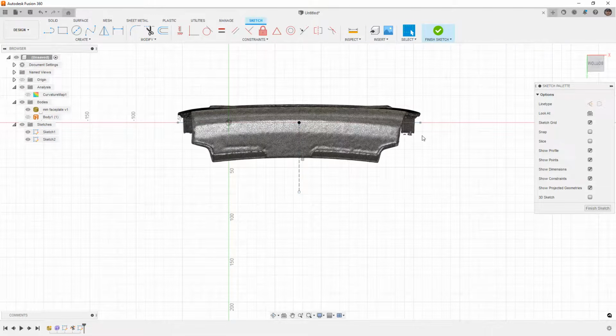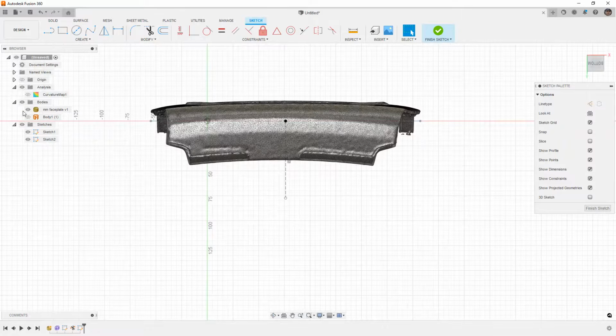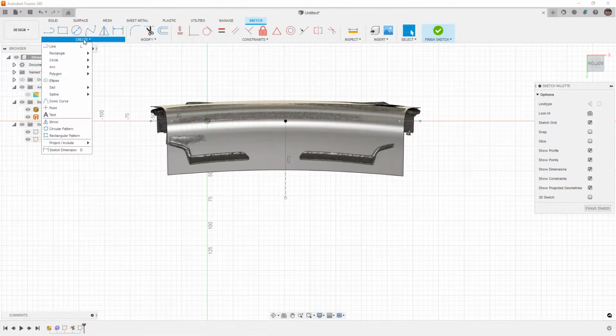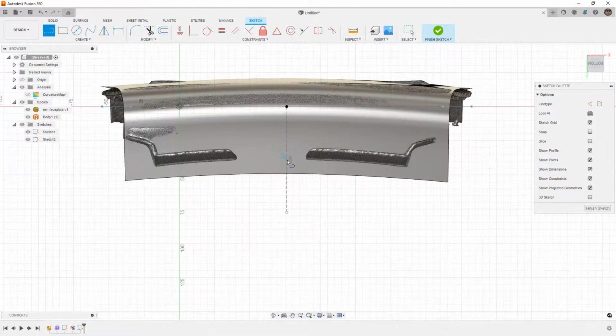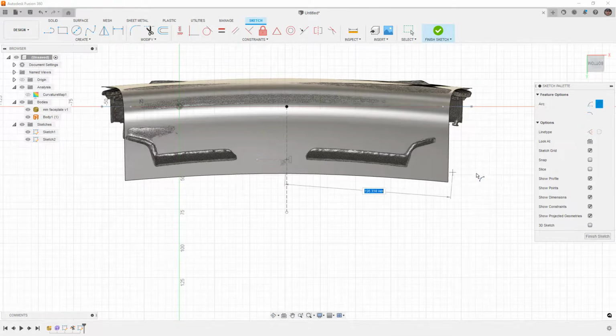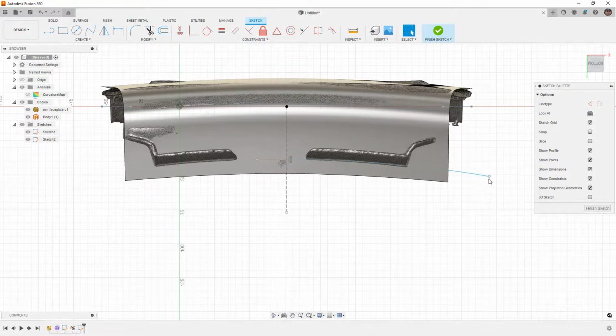And then we want to trim the rest of the surface. So at this point, we've trimmed it up to here. And then we need to create these little cutouts in this arc. So the arc itself, what I want to do is I want to start with a line. I'm going to make a horizontal line, make it construction, and then add an arc. So the arc here, I'm just going to bring it all the way out for now and make it tangent here. We'll hit escape, and we'll just simply bring it into where it looks about right.